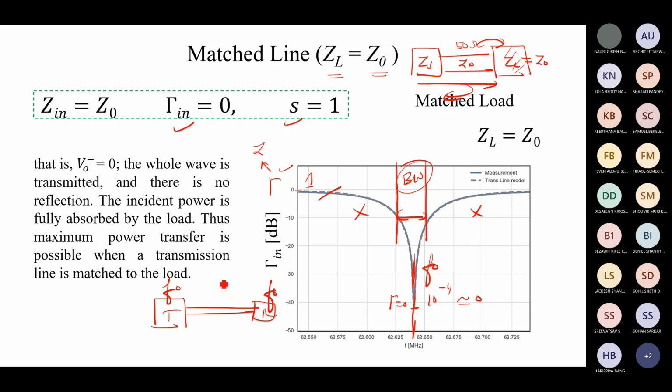If somebody wants to get the signal, they are supposed to use a very similar operating frequency. This is how the radio station works. You have to tune to this particular frequency. So what is actually happening? The load is nothing but your radio, and the antenna is there. The antenna has some impedance, let's say some ZX. Both are connected by a transmission line. Here we will make an inductor or capacitor. By means of tuning it, I can match this ZX with the ZL.